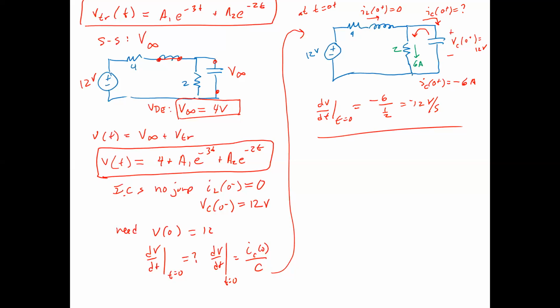However, the way we can determine the boundary conditions is that the inductor current is not going to jump from that disturbance. The capacitor voltage cannot jump from that disturbance, but everything else can jump. So that's the transient. The transient response is governing from 0 plus to sometime less than infinity, a lot less than infinity, right? Because at infinity, the transient goes to 0 completely.